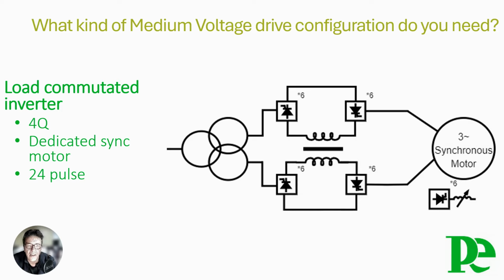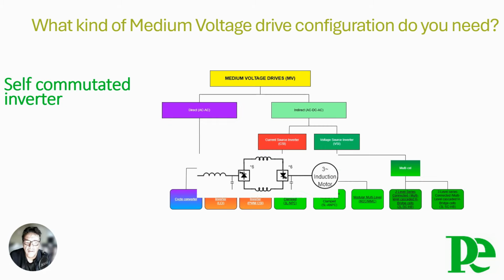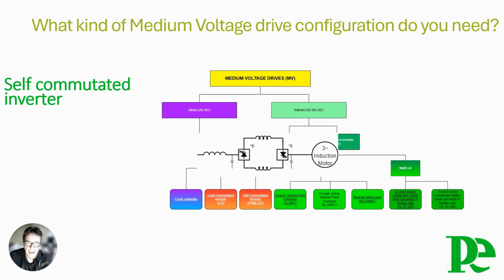In industry, power plants and ships, the LCI drives machines such as blowers, sinter fans, pumps, wires, rod mills, extruders, refiners, compressors, tube mills, boiler feed pump, marine propellers, thrusters, shaft generators, test stands. These inverters are often used also as starting converters for blast furnace blowers, gas turbine sets and large synchronous motors on weak power systems. We conclude the current source overview with the self-commutated inverter.